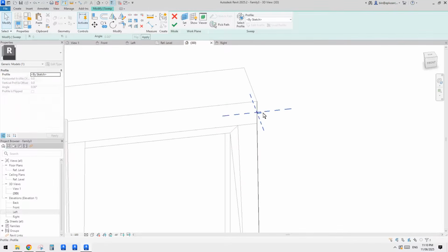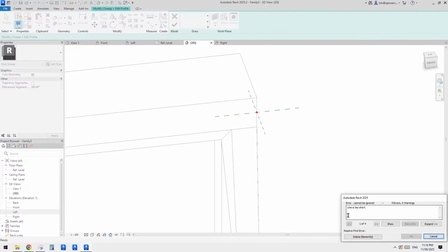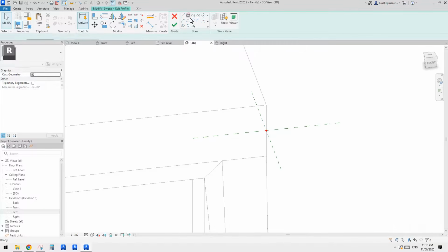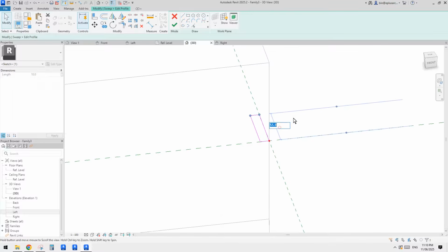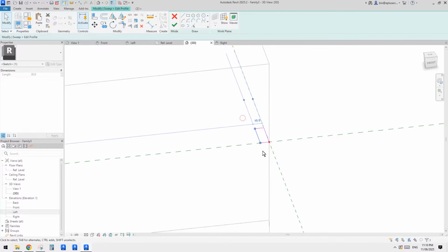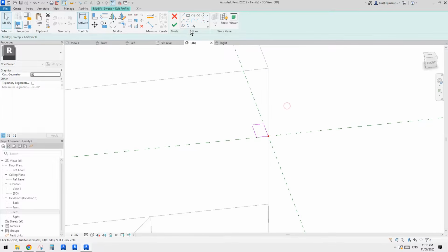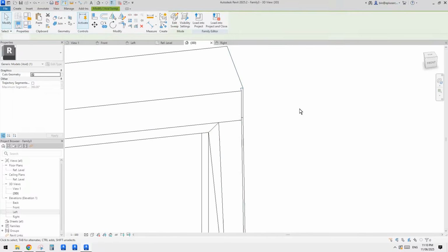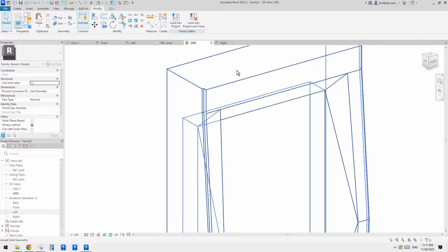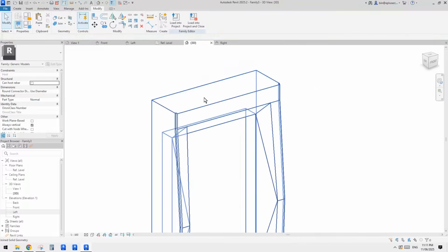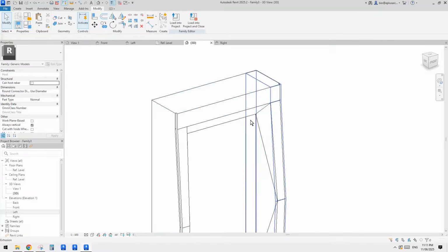Sorry, we just need to edit profile. Oh yeah, no idea what's going on. Delete. Just do a rectangular shape. Needs to be 30 by 15. Finish. It should automatically cut a void. Okay, so for this direction, we can just build that into the void or into the extrusion.